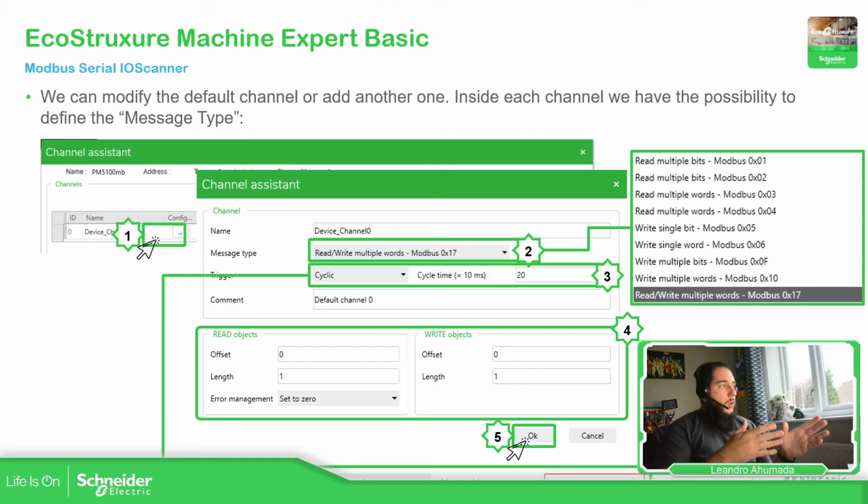So if you take a look, it's very simple. You just define the message type, which is basically where the variable is located on the other side in the slave. Then once you know that, you just need to define which function. Then you need to define in that area of the slave where that variable is located, and then you can specify, okay, from that position I want to read this many variables. That's basically the idea, read or write. That is the idea of using this.